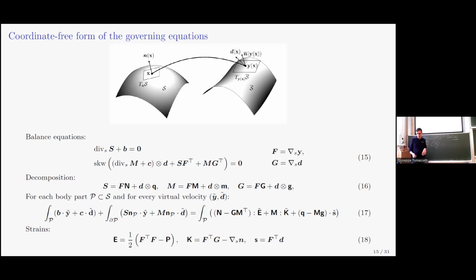It's a plane tensor. The second term is this part of the bending moment, multiplied by the rate of change of this curvature tensor, which is obtained by pulling back the gradient of the director to the reference configuration by multiplication with F transpose. If you look at this tensor just from the point of view of linear algebra, just to see the structure of this tensor: G is the gradient of the director, so it maps tangent vectors here into vectors here.